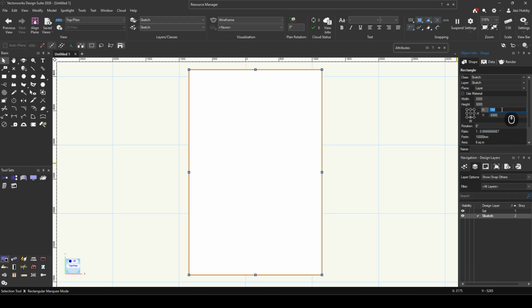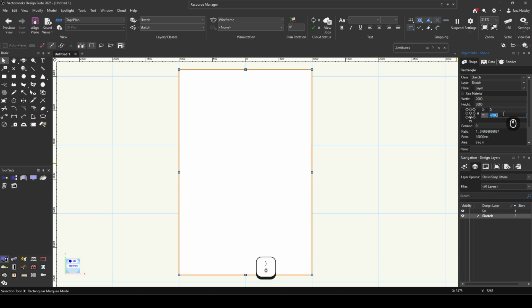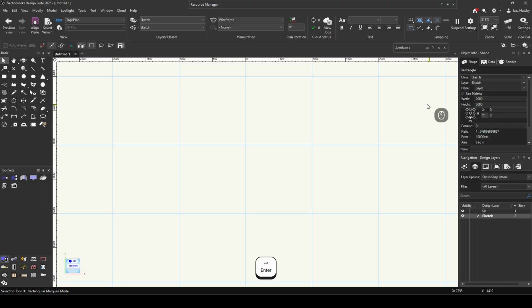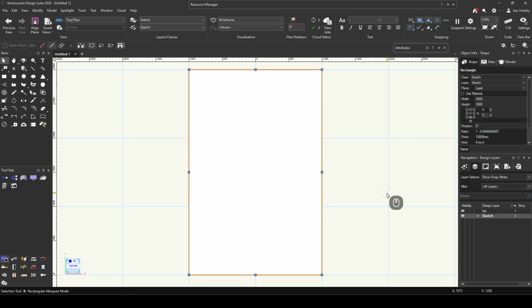If I highlight X here and press 0, highlight Y and press 0, this will disappear. Fear not. I press the zoom, fit to objects here, and it will reappear. And this bottom corner here is 0, 0, the internal origin. What that means is basically I could say something that's 600 up from this, or I can relate around this object.